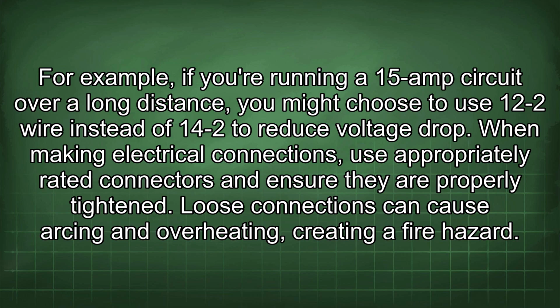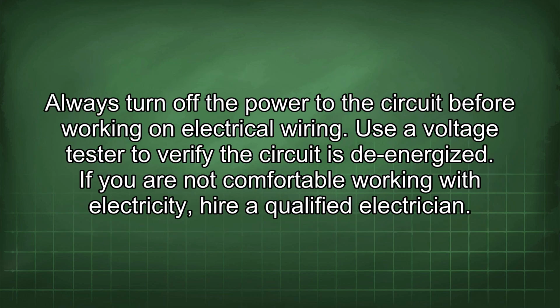Loose connections can cause arcing and overheating, creating a fire hazard. Always turn off the power to the circuit before working on electrical wiring. Use a voltage tester to verify the circuit is de-energized. If you are not comfortable working with electricity, hire a qualified electrician.